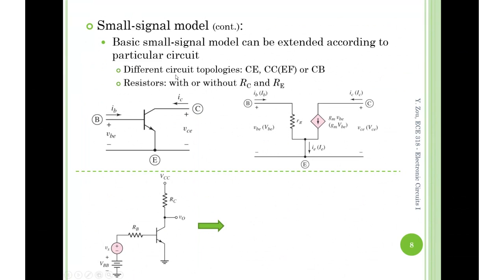Always follow such a procedure. First of all, place the small signal model of the transistor right in the middle of the paper, and then extend the circuit terminal by terminal, following such order. This minimizes the possibility of missing any element of the circuit.